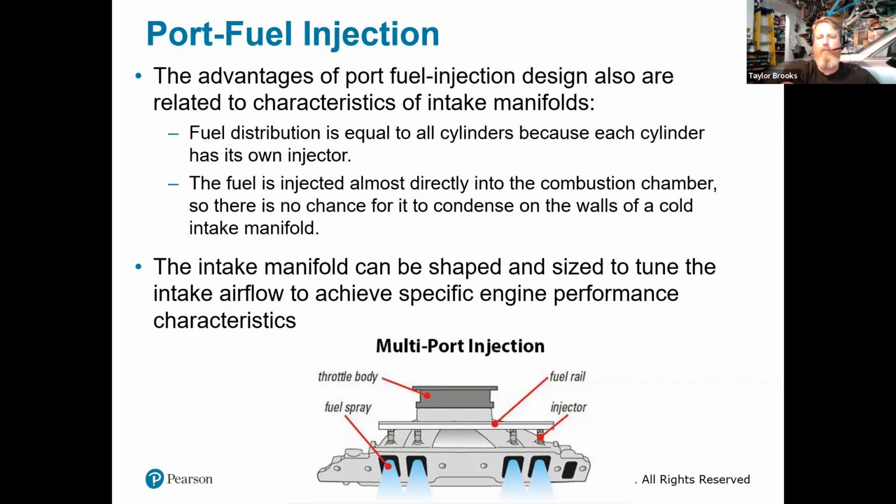When we started to see manufacturers paying more attention to fuel economy, as gas prices started to increase, we started to go to a more efficient design. And by far, port fuel injection is way more efficient than our throttle body injection. It brings the fuel injector closer to the intake, or into the intake valve. I keep getting that messed up. I'm sorry. And it allows for distributing the fuel in the most efficient way.